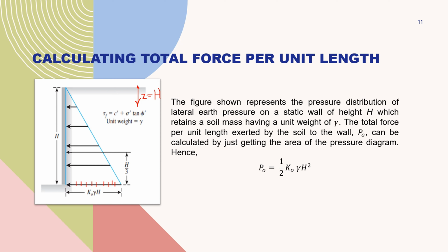To get the total force per unit length, we just take the area of the pressure diagram.